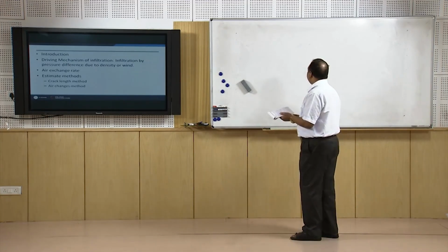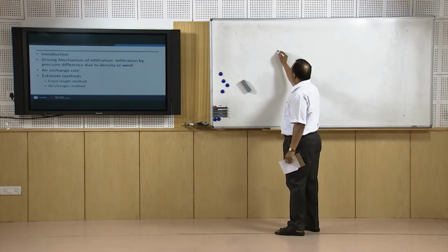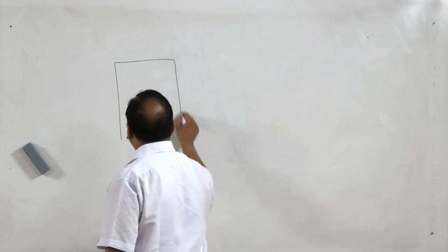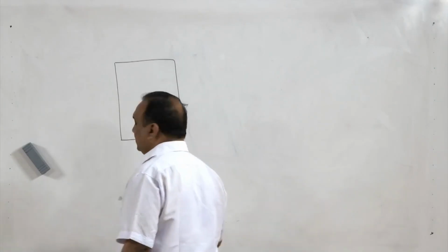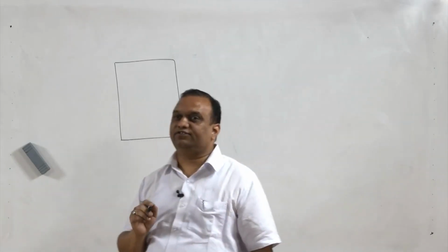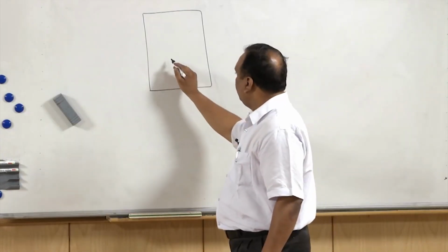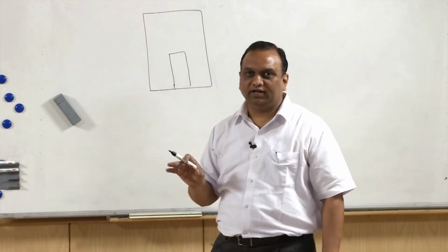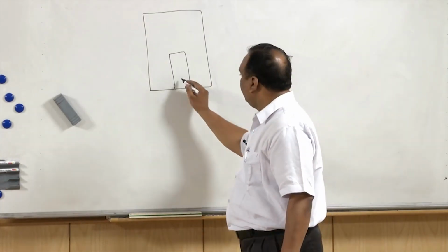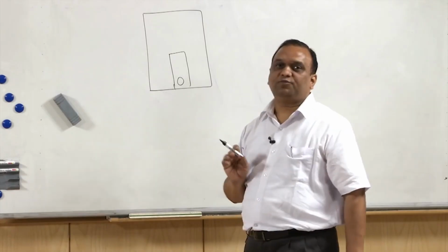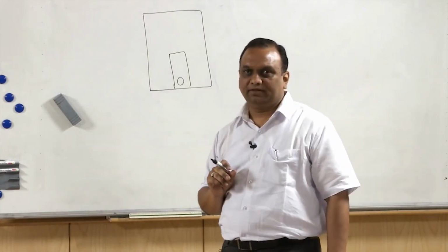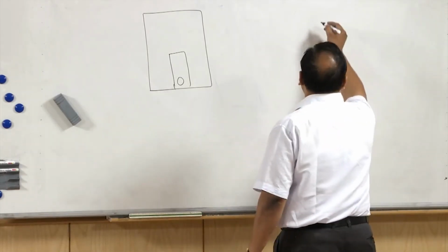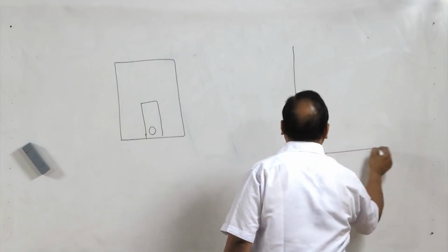A blower door test is done on the building. It is an air tightness test of the building. On a door, a blower is fixed, all the windows and doors of the building are closed, and a certain amount of pressure is maintained in the building.